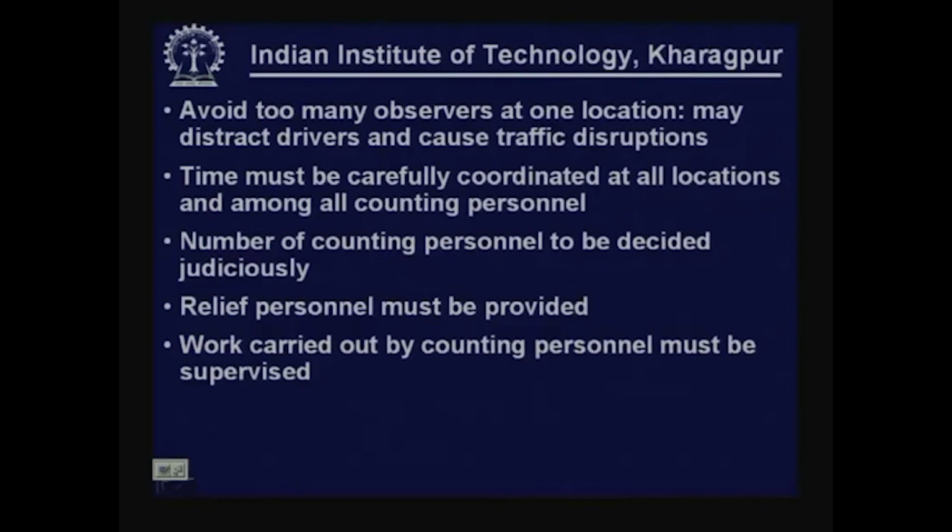Relief personnel must be provided, because we need the enumerators to count the traffic continuously. So, say for 8 hours a person cannot work continuously; he will require maybe a cup of tea, or need to go outside for drinking water, for taking rest for 5-10 minutes. So, you must provide adequate relief personnel, so that in rotation everybody gets a break. Otherwise, if you do not provide that, the quality of the work suffers, they will probably go away, and there will be no counting during that period.